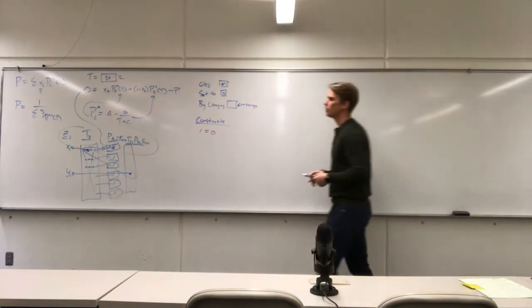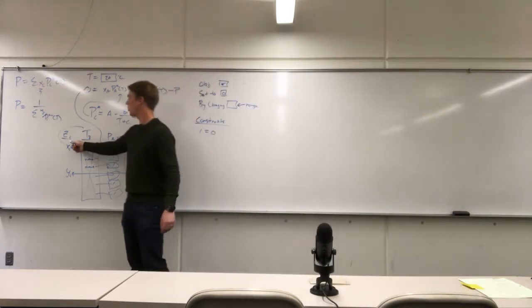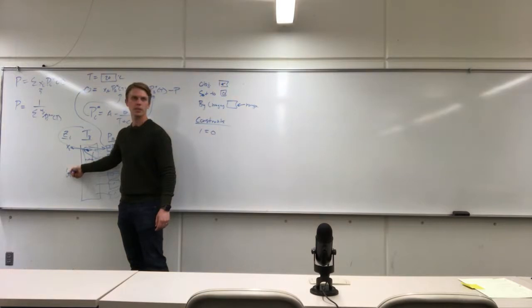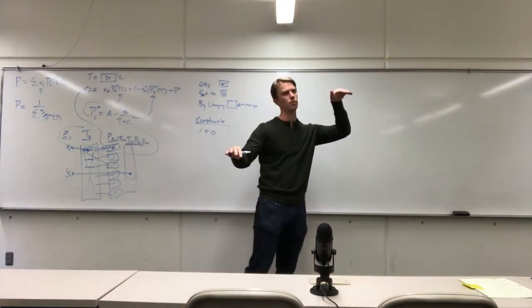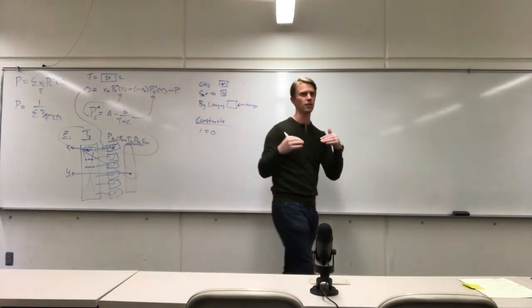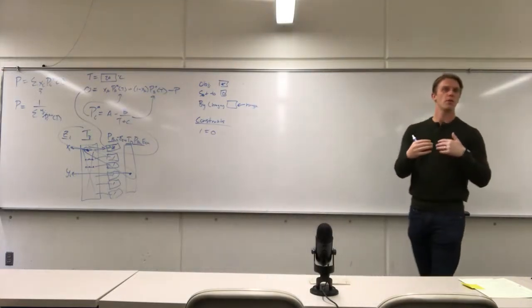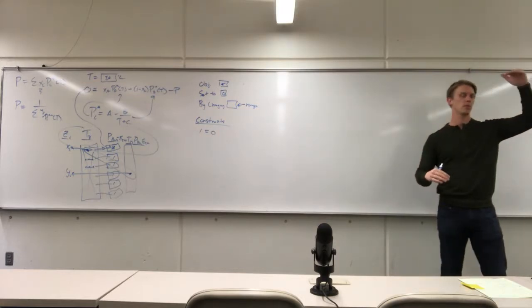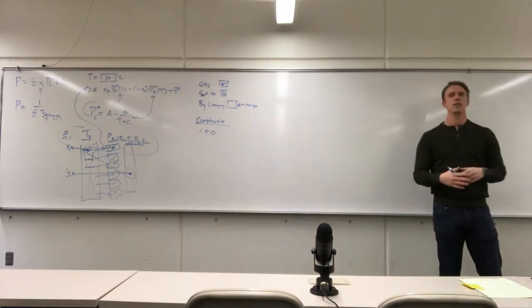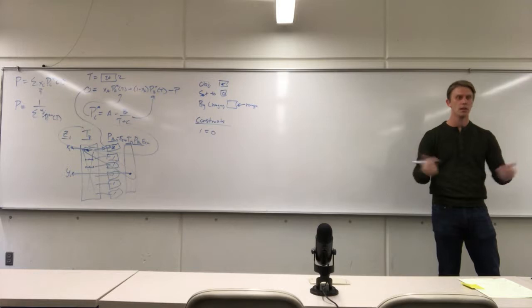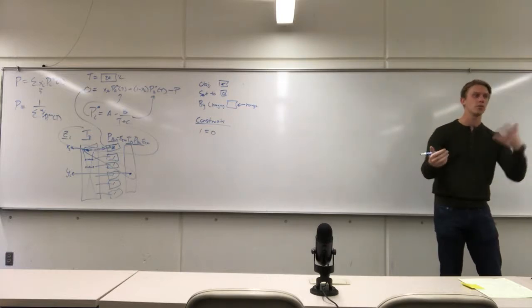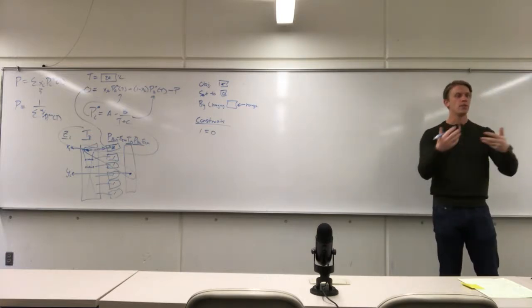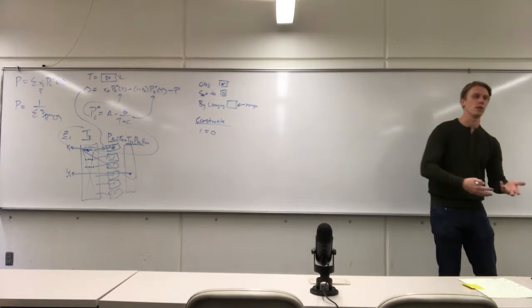Because let's say for example, you discretize your Z 0.1, 0.2, 0.3, 0.4, 0.5, 0.6. That doesn't guarantee that at some temperature your bubble curve is going to have the same temperature as your dew curve, because you've discretized it differently. But once you know your bubble and dew maximum and minimum temperatures, then you can repeat that calculation, but by knowing the temperature and making sure that the pressure is equal. So you can solve for X for a given temperature and a given pressure. And then you can use that to solve for Y, and then you create your XY diagram.